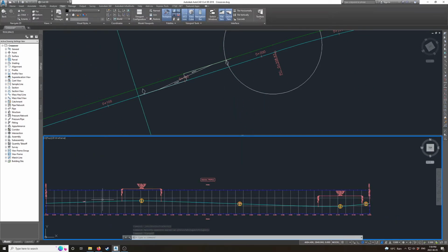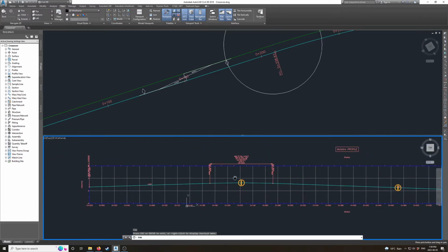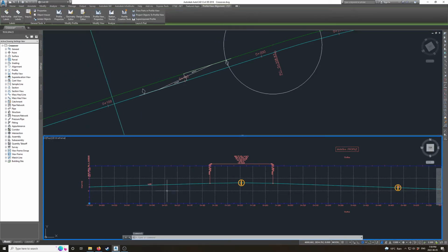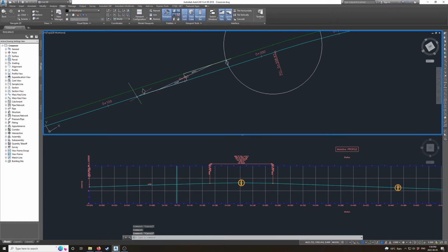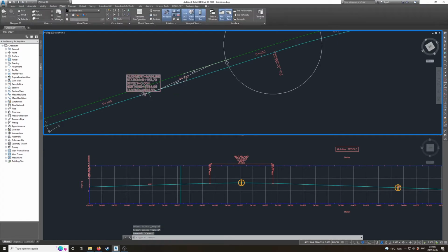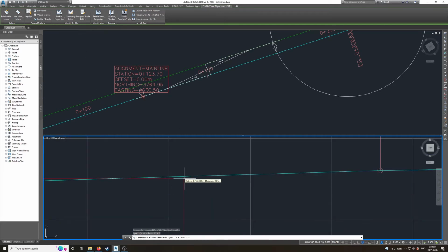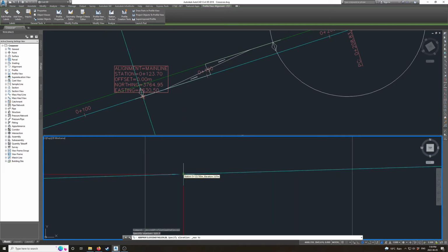This is a profile for the main line, and the profile for the siding can be slightly different, so we can potentially make this fit still. One thing we can do is figure out where we placed this turnout. It's 123.7. So if I do 123.7 and pick that,